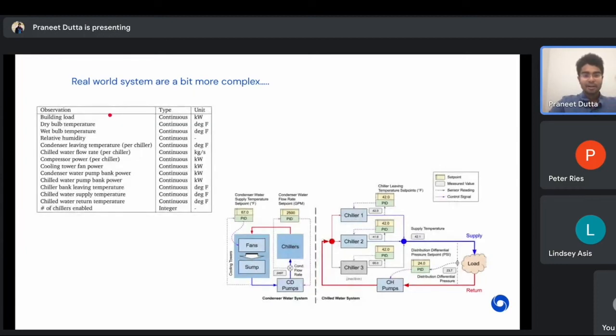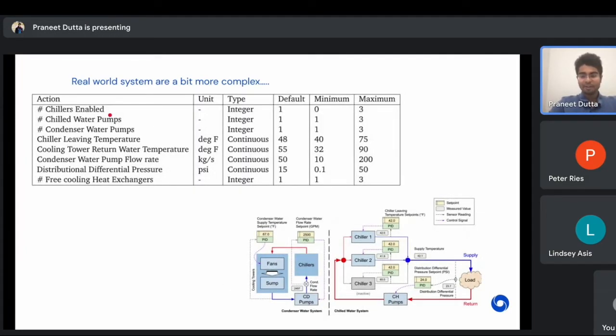But another point I will mention is that these systems are quite complex, big pieces of machinery. If you keep switching them on and off, there's a huge ramp up latency. Think of starting, and I want to say a car, but that's usually instantaneous, like a large ship or a large aircraft. There's a huge ramp up time when the engine completely ramps up, right? So when you think of this large space of optimizations, switching on and off a chiller is quite wasteful if done very frequently. And there are ways in which you can meet the requirements without switching them too frequently or changing set points too much, because those consume energy.